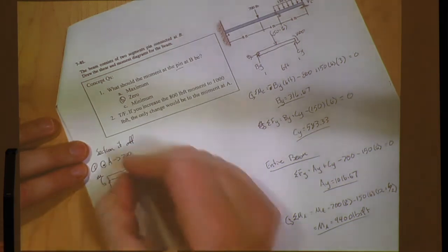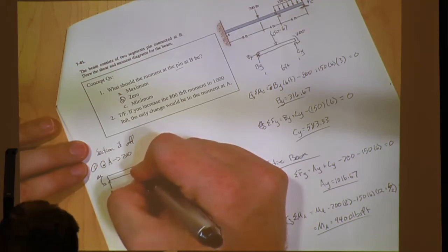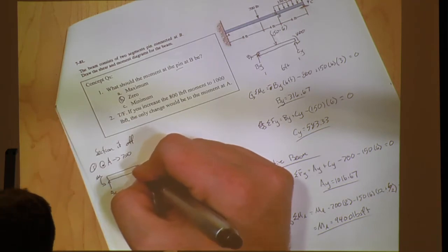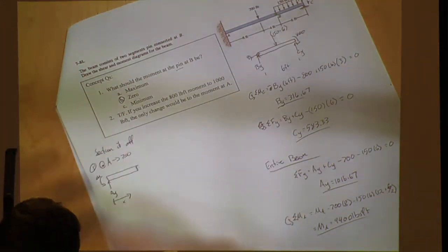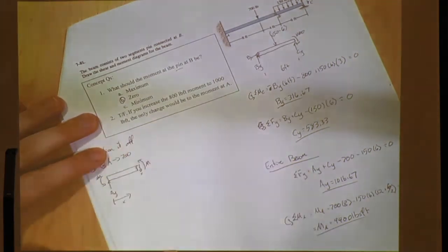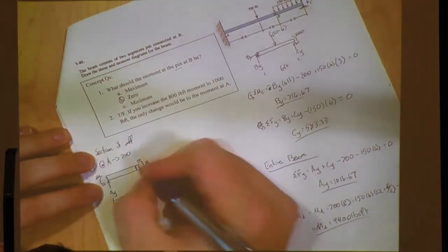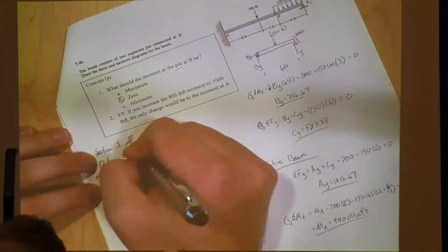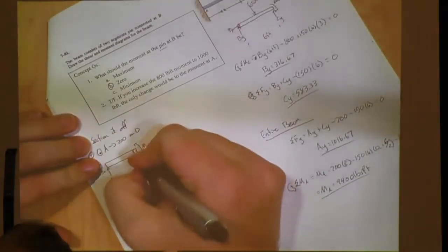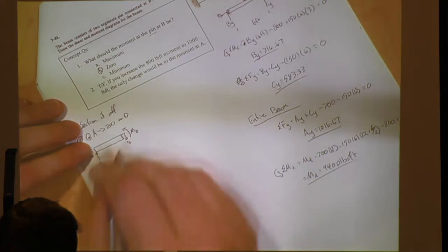And then what's our convention for shear and moment? For the left-hand side, shear down and moment always separating it up and out. All right. So we just call this point D. So this is VD and MD. Not that VD, please.